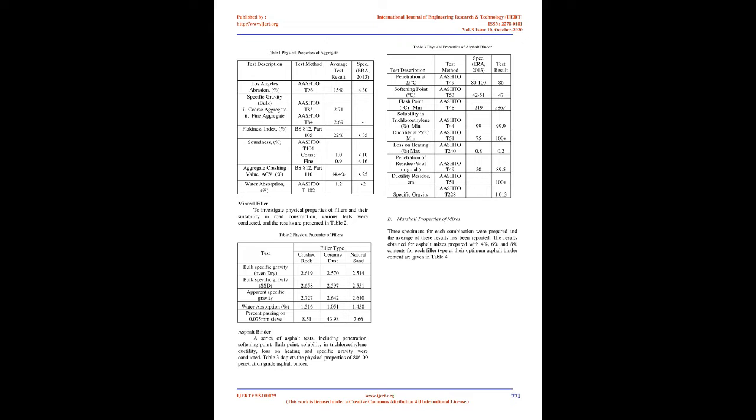Moisture damage in asphalt mixtures refers to loss in strength and durability due to the presence of water. Many variables affect the amount of moisture damage which occurs in an asphalt-concrete mixture. Some of these are related to the materials forming hot mix asphalt, such as aggregate and asphalt binder. Others are related to mixture design and construction, air void level, film thickness, permeability and drainage, environmental factors, traffic conditions and type, and properties of the additives. The presence of moisture, combined with the repeated action of traffic, accelerates damage to the asphalt pavement.